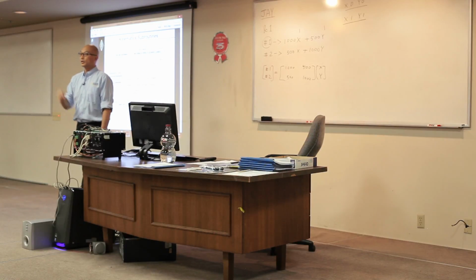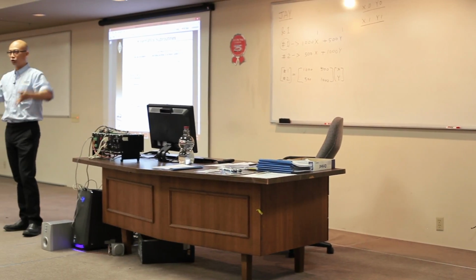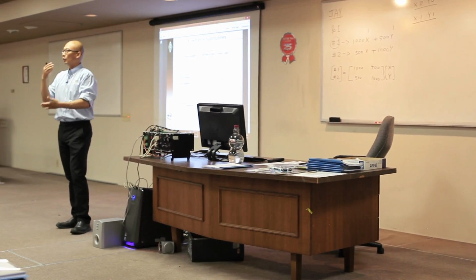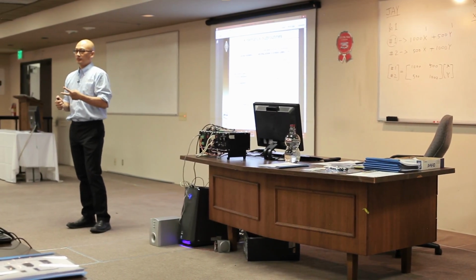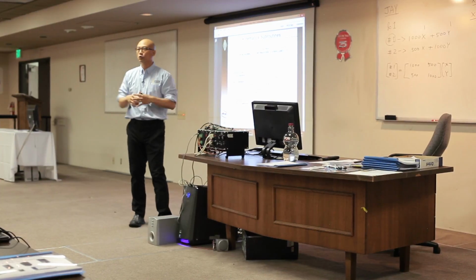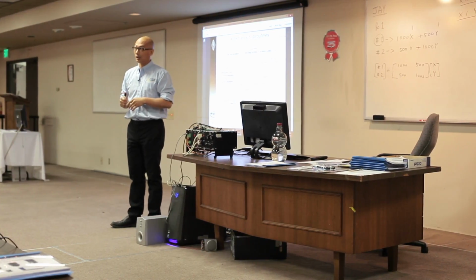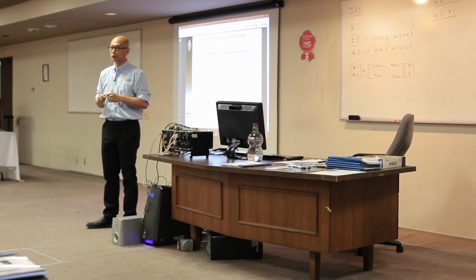Okay? So when we talk about the axis definition, we actually give you a huge, giant matrix, right? Because one coordinate system can actually control up to 32 axes under one coordinate system. So we have a giant 32 by 32 matrix to actually say, okay, this is the calculation that we want to use.